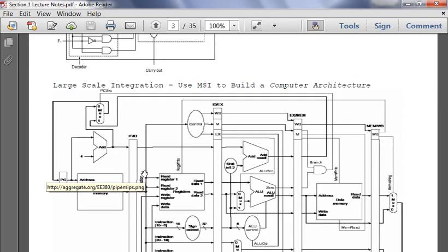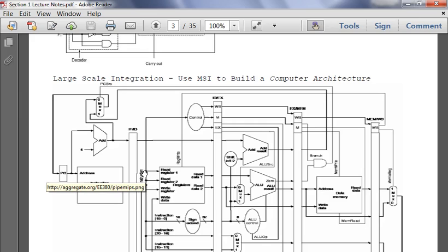Look familiar? Yep. Hey, for those of you who haven't had my class before, this is the MIPS data path. We have the instruction memory here. We have an adder. Registers store local memory. Arithmetic logic unit and adder to perform branching instructions. Then we have data memory, so it's like the higher DRAM type memory, or the memory hierarchy, and then we go back and do it again. So without going into too much detail, this is an example of a VLSI circuit.